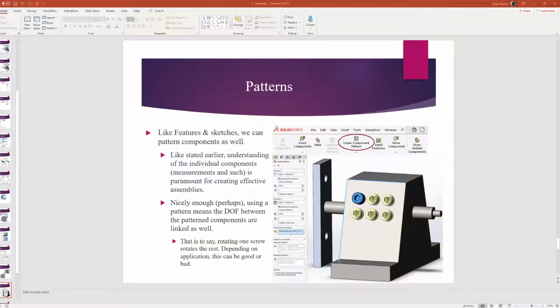So I'm just going to say, okay, cool. These sides are 4.5 from one another. If I go, oh, I don't even have to. In assembly, we can also create reference geometry. So I'm going to click that and hit plane. I want it based upon this side, and I want it to be 4.5 divided by 2. Not the correct direction, I want it right there. Looks pretty darn good, and I'll hit OK. It's a small plane, but it doesn't matter. It extends off into infinity.